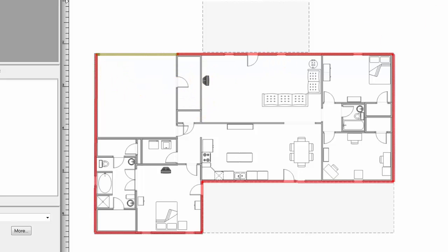Alright, so you need to go through here and do all of your wall types, and I mean all of them. So you'll want to go through and select every single wall in here. You can do doors if you want to, but I'm not a big fan of doing doors. I usually just draw a wall over the top of them, because a drywall and a wooden door are roughly about the same dB loss. So you'll want to go through here and populate all of your walls.